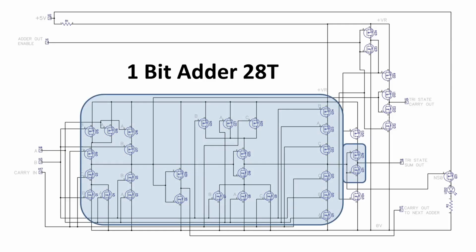So these are the actual transistors that do the adding. You can go through all the logic of what ones do what if you want. It's a little bit confusing. It gives a carry out, so that can feed onto the next bit. And there's a carry in as well on the left. The one adder feeds onto the next. And when you get to the end of the board, you just feed that board off onto the next one. So you can daisy chain them. I've done an 8-bit adder. You could do 12, 16, 32, whatever you like.